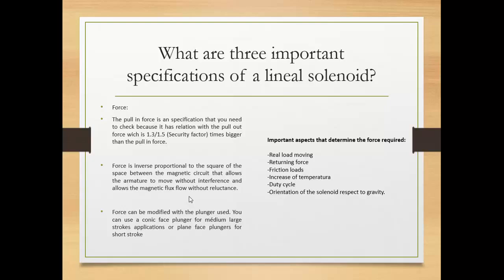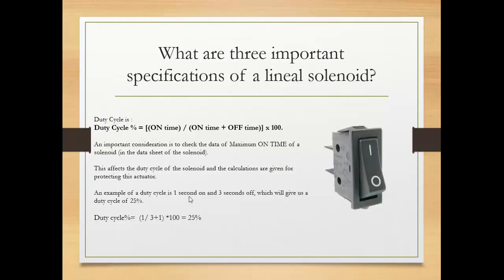Other important aspects to consider when you calculate the force are the real load that you're moving with the solenoid, the returning force of the solenoid, the friction forces or loads that will be generated, the increase of temperature, the duty cycle, and the orientation of the solenoid with respect to gravity, because it also affects the force.